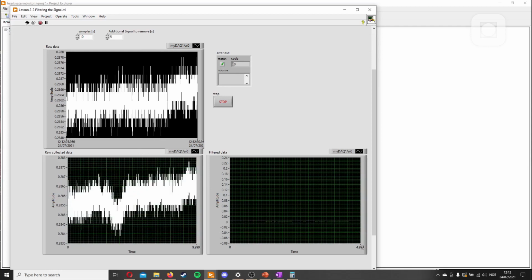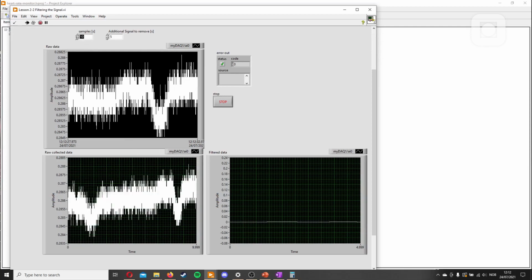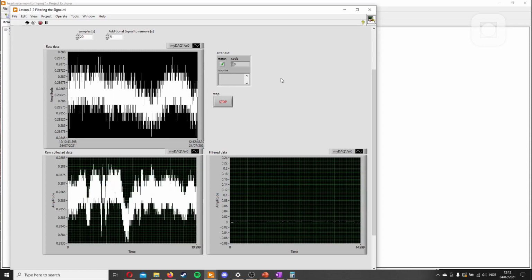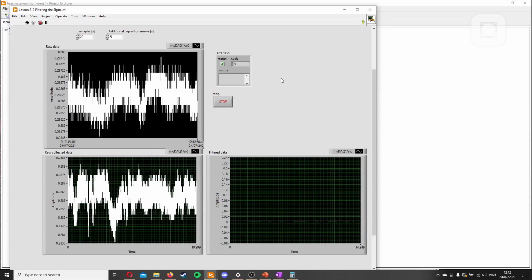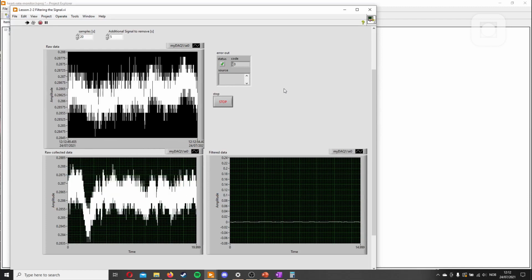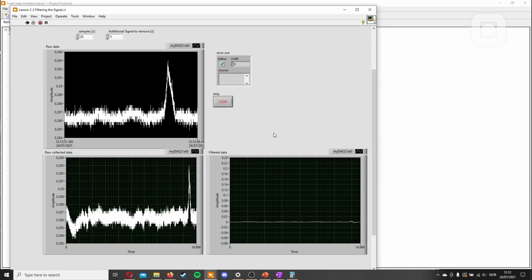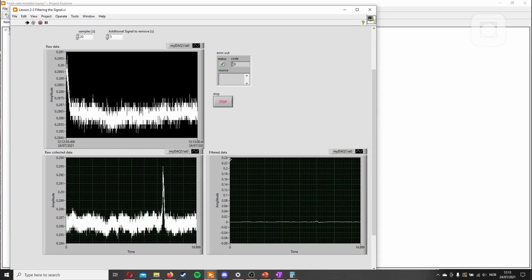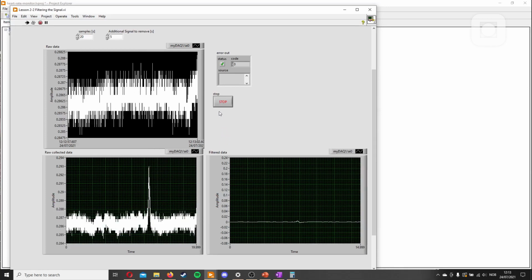We got half the signal length, but that doesn't matter because we can just increase it here. The filter takes the same amount of time to stabilize regardless of the length of the signal. So this works out fine. But 5 seconds is a lot of time, so let's try to minimize it with some fancy technique.